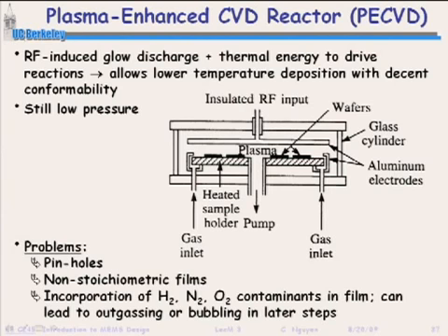Okay, well, in an LPCVD furnace, the temperature is uniform. In a PECVD type situation, you're at high temperature, but the rest of the energy is coming from the plasma, and maybe that plasma isn't getting to some spots. And so that means you don't have the energy going to those spots, which means you have a point where there's no reaction. You've got film everywhere except for that little pinhole there. It could be a minute pinhole. It could be like 10 nanometers wide or so. But that 10 nanometer wide pinhole could kill you, especially if that film was supposed to block an etchant that's coming afterwards from reaching the film underneath it.